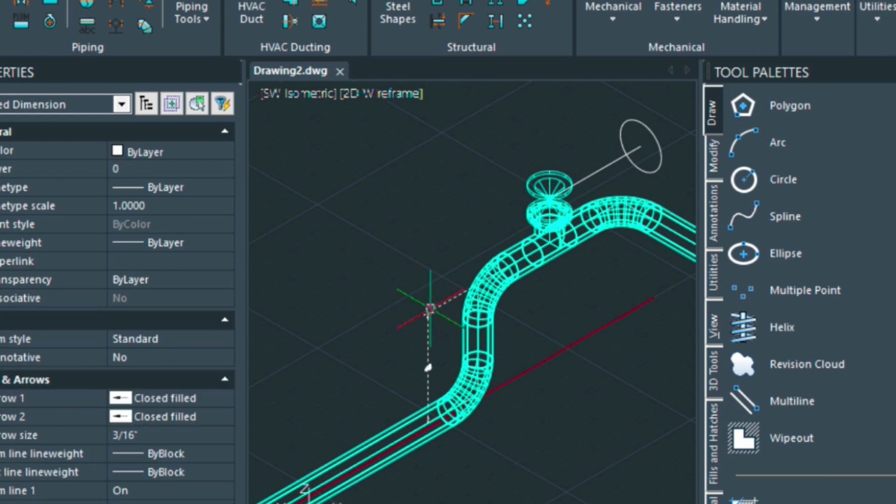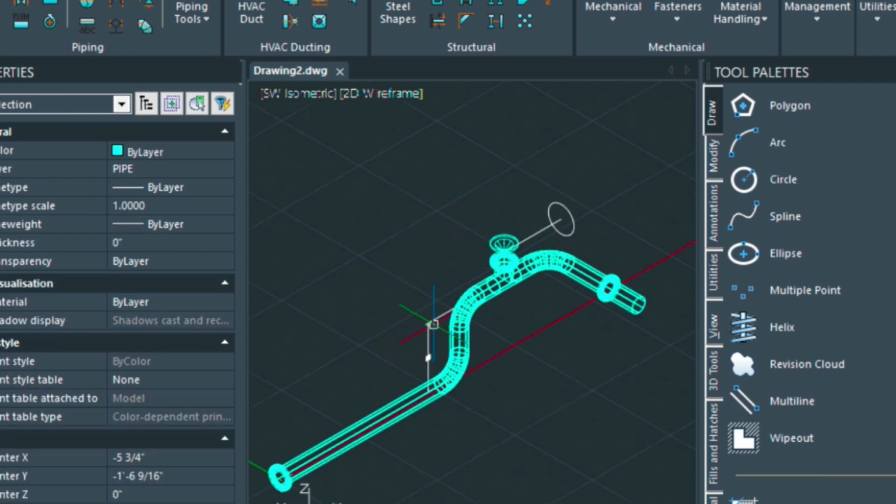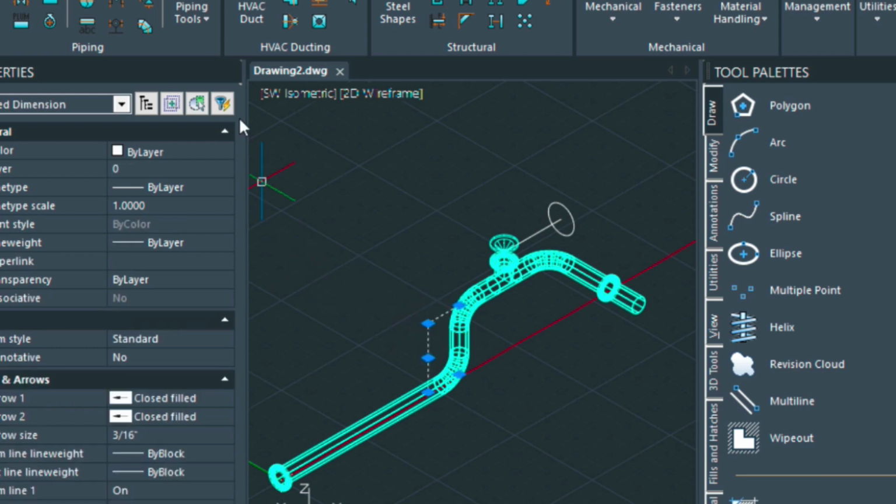layers. Now layers essentially are ways we can organize our drawing more efficiently. When we created this dimension line, we put it on the default layer of 0. So what we really want to do, since we really want this dimension line, is move this and put it on the text layer, for example.